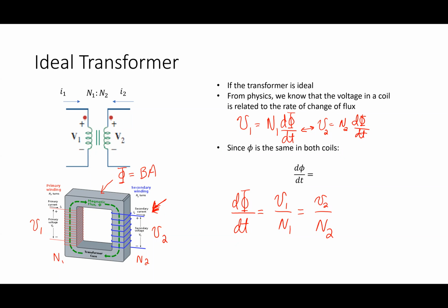Wouldn't they be inversely proportional? Yeah. And why would that be? So current, if voltage goes up, current goes down. So what if you think about what would happen in most circumstances? I'd have a voltage source on one side and a resistor on the other side. The way I think of this is in terms of power flow. Where's the power coming from and where's it going in that circuit that I drew right there?